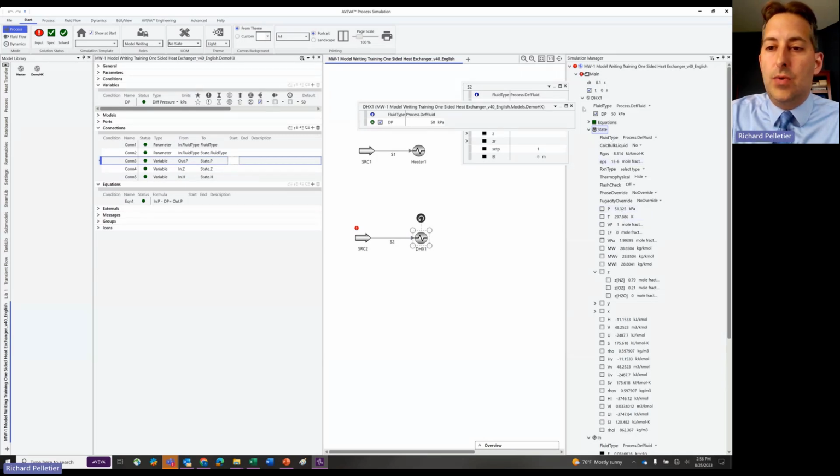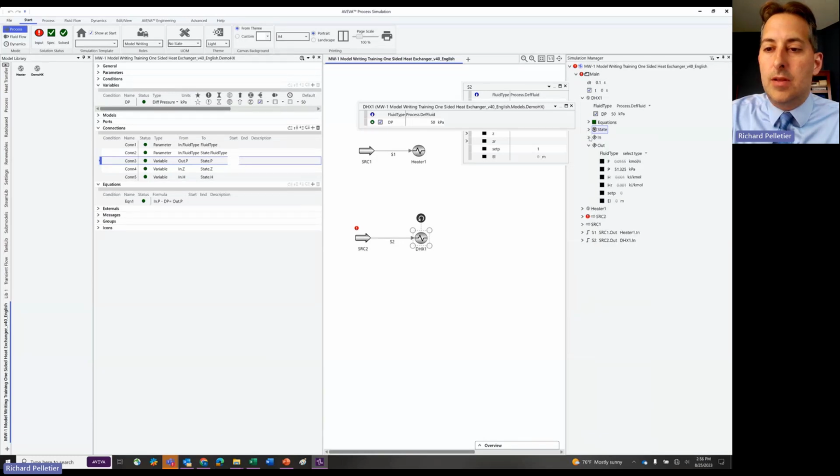Right? Now, we added that outlet stream, and we have properties here that aren't populated. And so one of the things that we can use is, even though we're square and solved, the fact that these are grayed out means they don't belong to anything. Nothing is populating them. Nothing's calculating them. We still know that we need to provide these pieces of information.